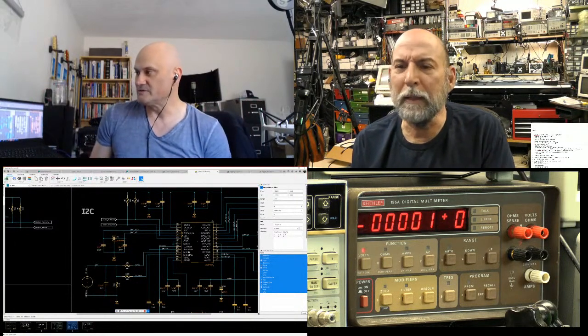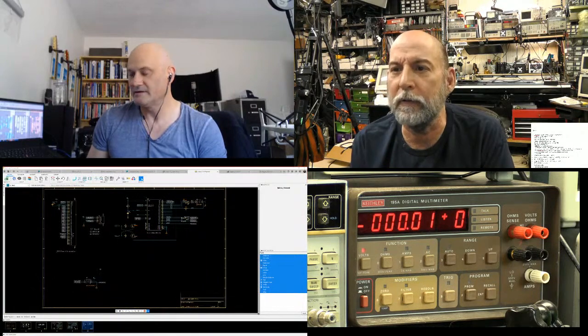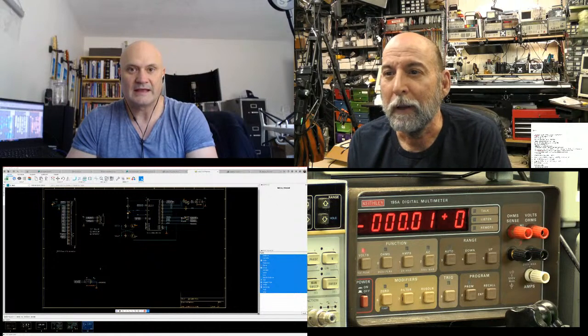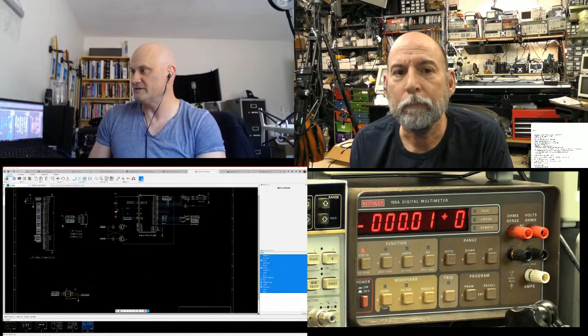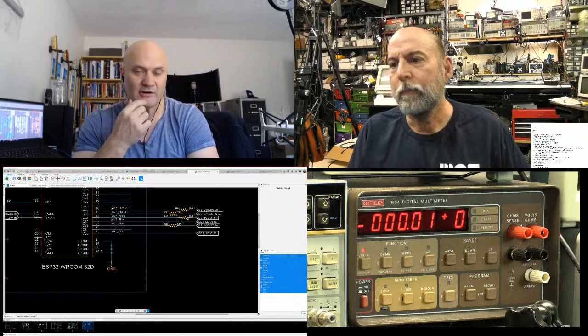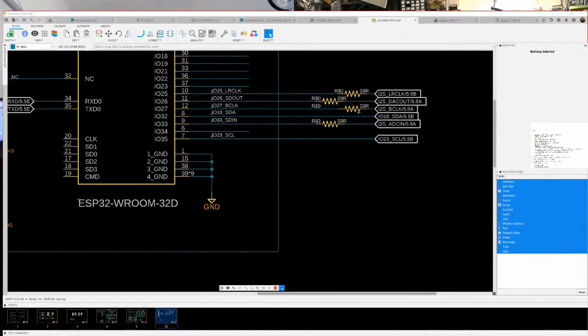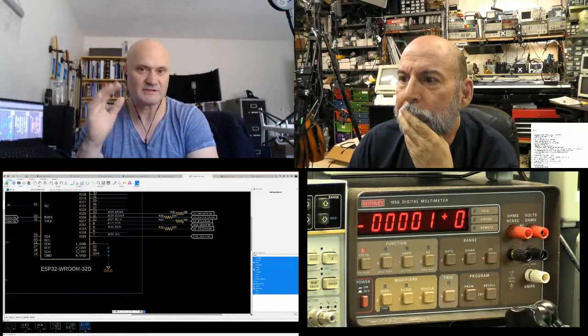Yeah, well, that to me implies a true dual port RAM in the middle, because then you need a way to clock into some kind of storage and clock out of it in an unrelated way. And that sounds like a dual port RAM function. I don't know the internal workings of the ESP32, which is hooked up to this for the I2S interface, but the ESP32 and any microcontroller that has an I2S port will be a slave to the converter. And that means you do have different clock domains. So the codec clock is completely free running and separate from the microprocessor in the ESP32 module. And so they must have some kind of clock domain crossing and synchronization.